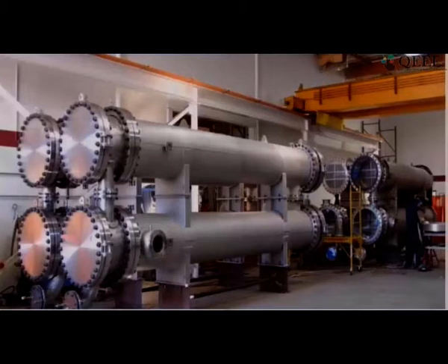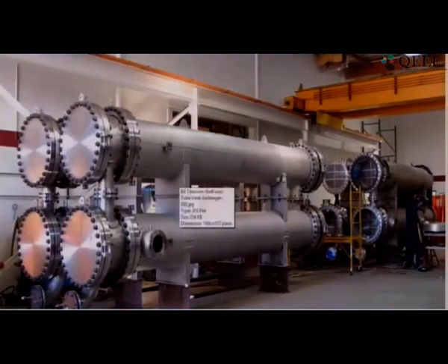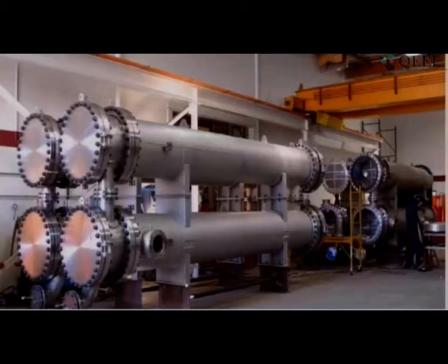There is an example of a finished device here. You can see that this is the shell. It has been mounted on supports, and instead of just having one heat exchanger, there is one over here and a second over there, and there is a combination in which either of the two fluids can go either in parallel or in series between these. These are the finished ones, so the ends have been closed with an end cover with bolts on it, and this is the one which is still open and has not yet been closed. So you can see the tube plate, the ends of the tube openings on this side, and on this side is the tube cover plate.